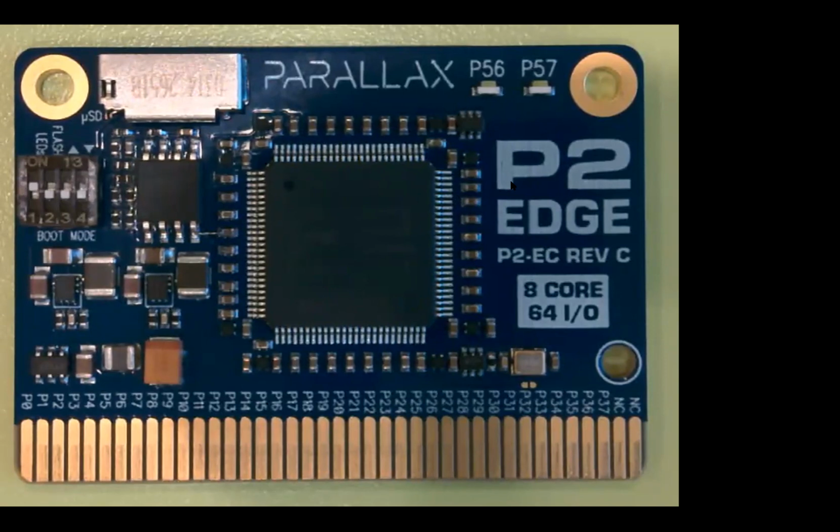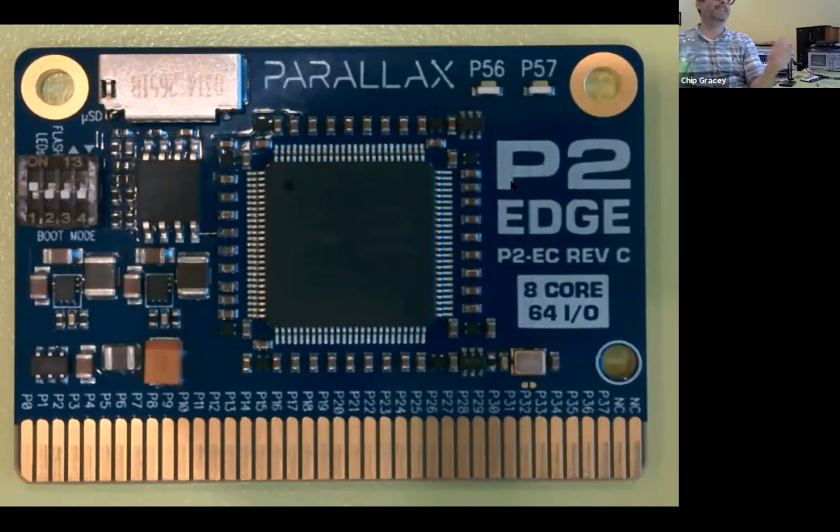One more. This is the unique modification you need to do in the board for it to work: the ground wire and a pull down resistor at one of the data lines. Is that true? Yeah, that's what we can do to get this working, but there's still some ground signals up here that are not connected.